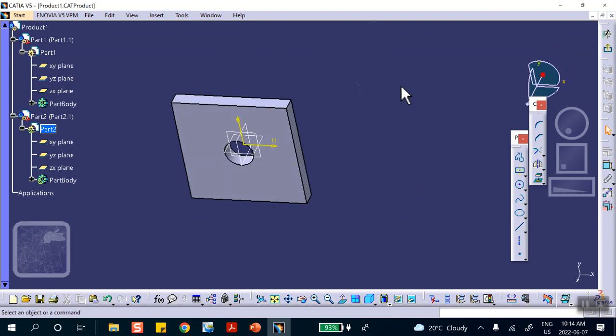So what I'm going to do is, here's what happened. The mistake that I made, I projected that circle, which is fine. Then I also projected that face. So there's going to be a circle on top of a circle when I try to clean it up and pad it, so there's an extra circle there. So I'm not going to make that mistake here. I'm just going to project that face. When you project the face, it does the whole thing, goes down. It's going to give you a rectangle, yellow rectangle, and yellow circle. Okay, so let me do that.